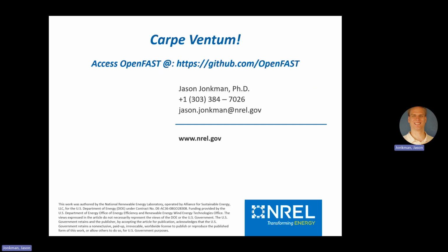So what Emmanuel's saying is, in the time domain, where we're just looking at out files, a few digits of precision is usually fine for time series. But if the goal of linearization is to do things like an eigenanalysis, we found that the bigger the system is, say 100 by 100 degrees of freedom, if we don't have high precision on linearization, the eigensolver basically gives you garbage. It's not that the linear model is wrong, it's just that there's not enough precision in that model, so it's an approximation of the real linear system. So we always recommend linearization output in double precision.